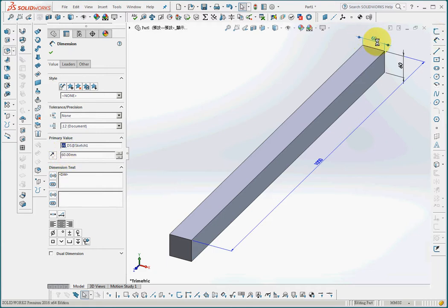We will name this horizontal dimension as width of the beam, W, and ds is the code to transfer parameters onto ANSYS. So if you rename a dimension as ds, ANSYS will recognize that this is going to be a parameter. So we do the same thing for the vertical dimension as h, the height of the beam, and ds is also the keyword for parameters on ANSYS. So we'll tell ANSYS that these two dimensions are parameters.